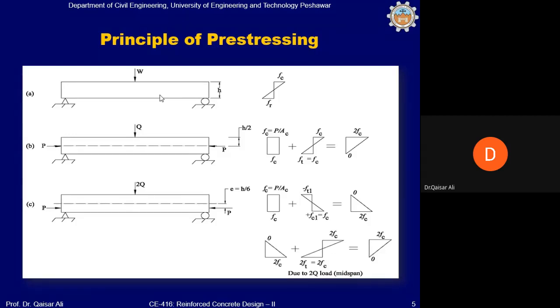So flexure stress is 0 at the neutral axis, and at any other depth, the flexure stress can be plotted, with the maximum values occurring at the extreme top and bottom fibers. The top fibers will be compressed and the bottom fibers of the beam will be elongated, or in tension.